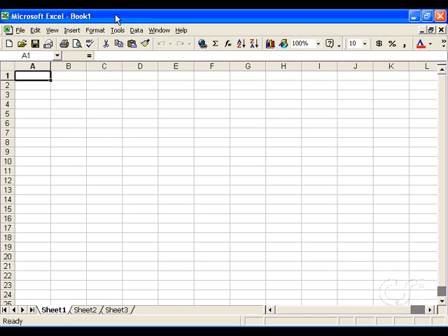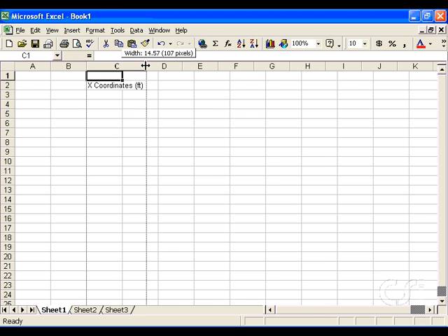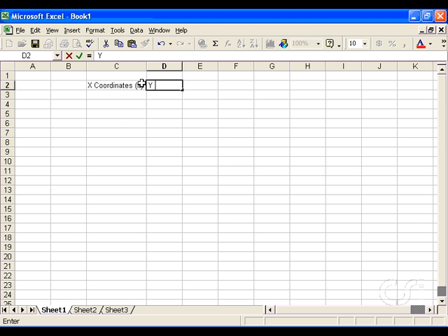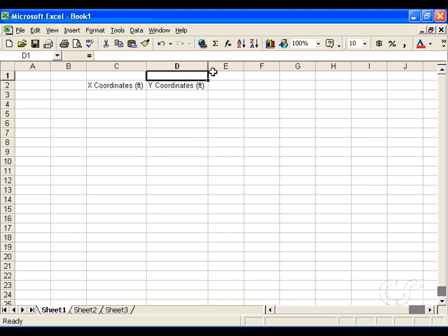We will control SAP2000 from Excel using VBA. We will also define the geometry for the model using Excel. We start by defining a column for the x-coordinates of the girder. Next, we define a column for the y-coordinates. Lastly, we will define a column for the vertical displacements along the bottom of the girder, which will be extracted from the SAP2000 analysis and written into Excel.